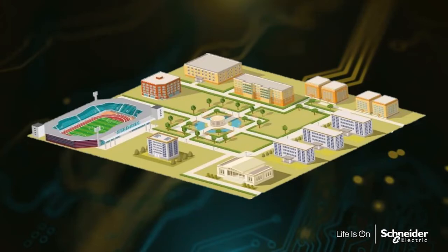They provide, critically, power quality analysis, which will tell you not only how your assets are performing, but what the power is like being delivered to them. So, for example, it will check the power factor and if there are any harmonics or spikes or sags or swells on your signals.